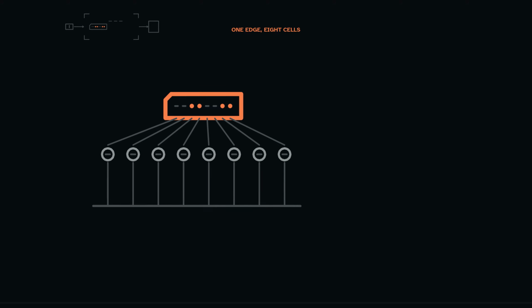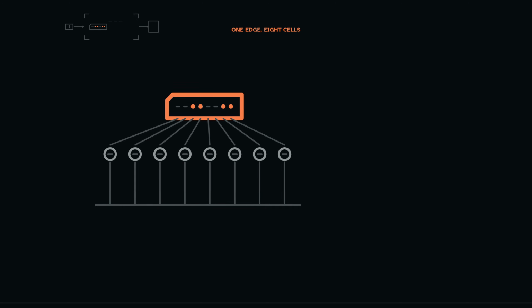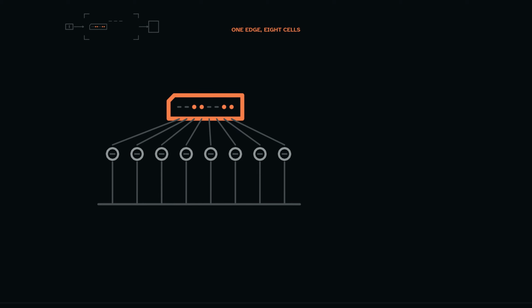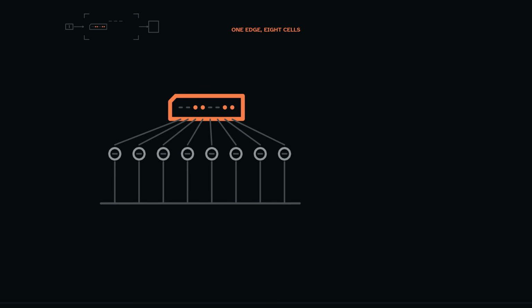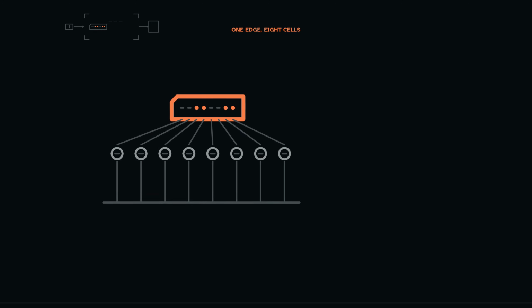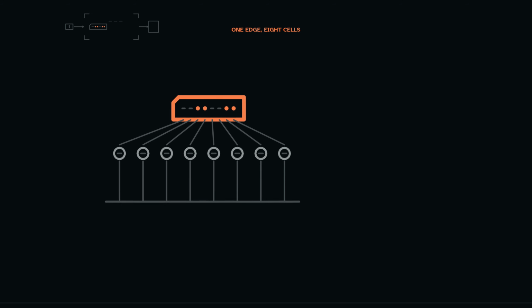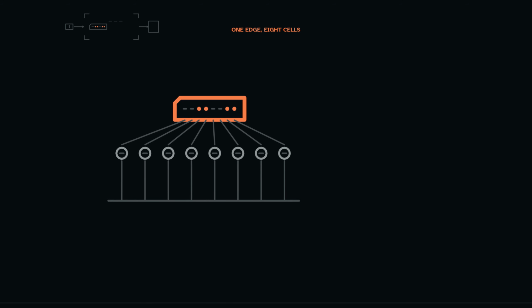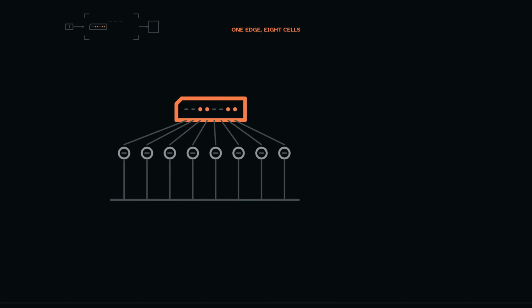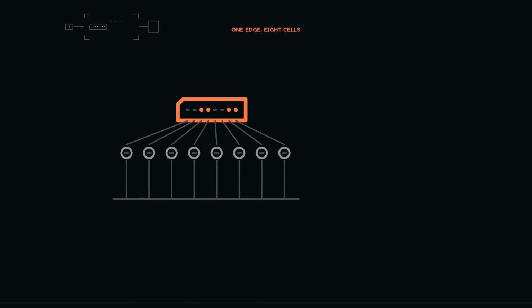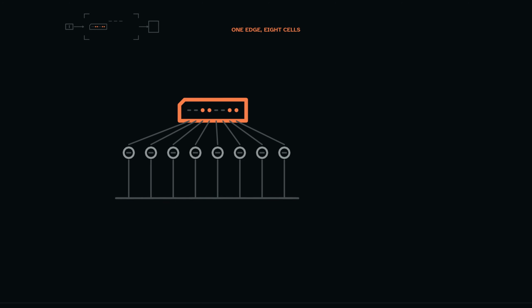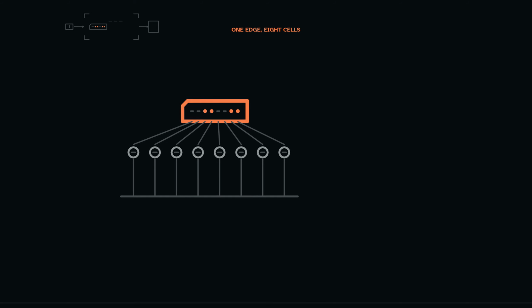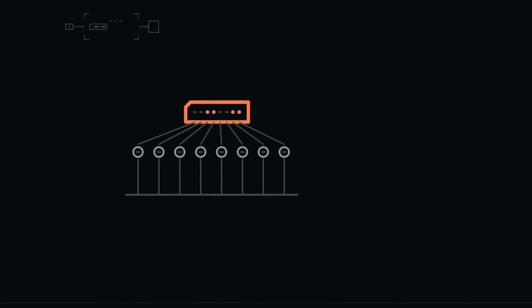A register is storage with a declared width and shared control used to preserve an ordered pattern as one machine state item. The word register names the container and its capture contract, not the meaning of the bits. The same stored pattern could later be interpreted as a number, character code, instruction field, or raw flags. The notch remains visible because reversing position order would change the pattern even if every cell kept its individual value.